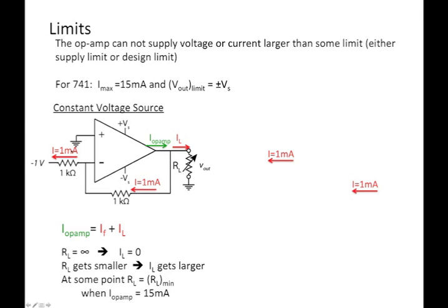And so we look at that, we go, oh, well, the gain is going to be the ratio of the resistors. In this case, it's 1. So we put minus 1 volt in. We're going to get 1 volt out on the input. So now this is where we actually want to use it, right? Okay, we got 1 volt out.